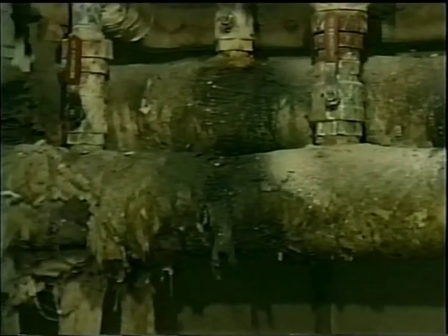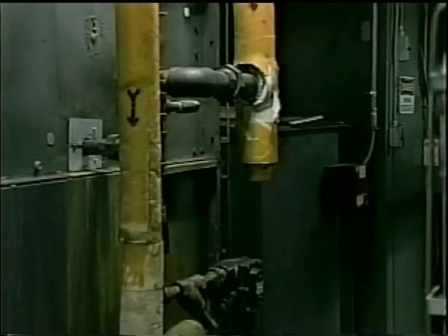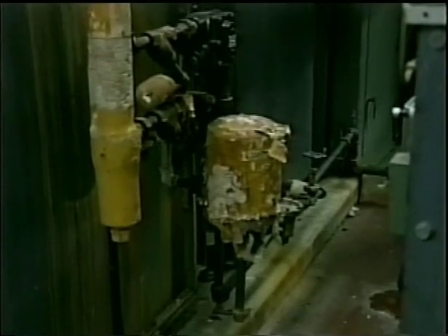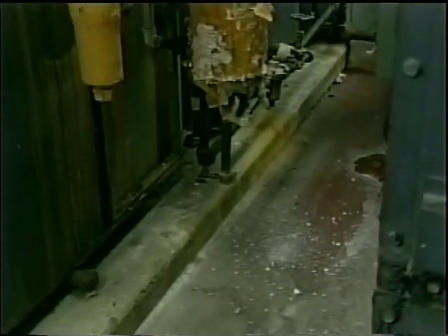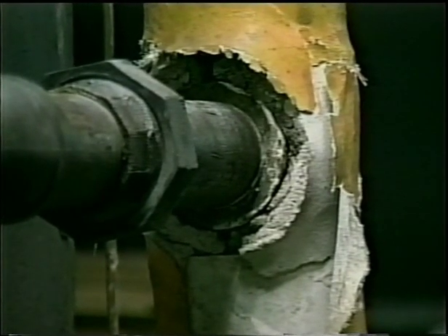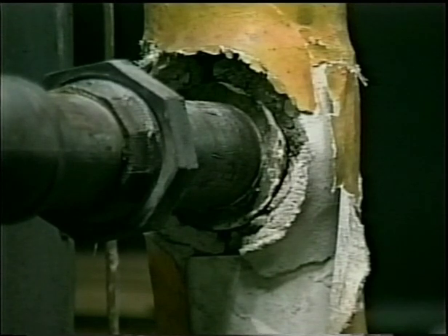Asbestos pipe and boiler insulation does not present a hazard unless the protective canvas covering is cut or damaged in such a way that the asbestos underneath is actually exposed to the air. Damage and deterioration will increase the friability of asbestos-containing materials. Here is a picture of damaged pipe insulation. Water, vibration, and maintenance activities are probably all partial causes of the damage to these materials. The damage has exposed asbestos-containing materials to the air. These materials are all friable, and if they're crumbled or damaged in any way, they will release fiber into the air.